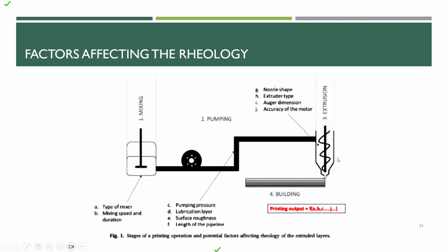It's also critical, very critical, but generally in a robotic system we try to follow a specific kind of cement with specific requirements, and mostly we use the same cement, so we have a lot fewer problems. But in a gantry, where the extrusion speed is a bit slow, we have to be very careful with this, and we just observe the layers, and increase or decrease the extrusion speed depending upon the actual layer.